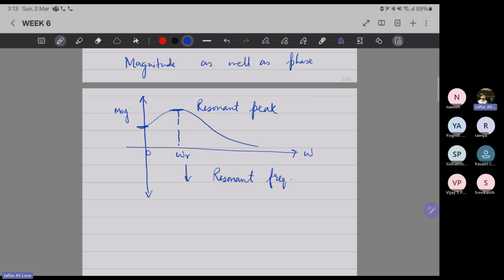So why am I recalling all this? Because at the beginning of the lecture, I told you about rise time, peak time, settling time, and maximum overshoot, and based on that, you can identify whether my system is good or bad, whether I can use it in my application or not. Similarly, based on these properties, you should be able to know how the behavior of a system is. If I tell you your system has a resonant frequency of this and a resonant peak of this, you should get an idea of how my system should be, right?